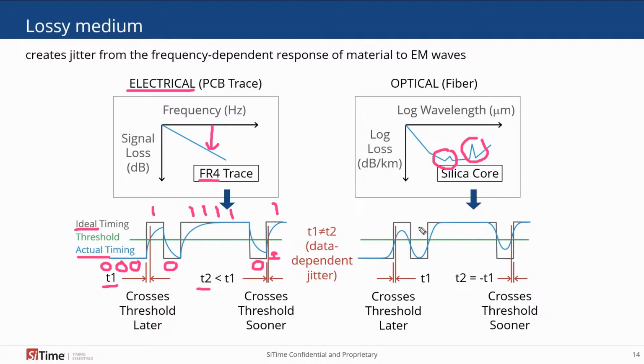And each wavelength propagates through the optical fiber at a different velocity. So some of those wavelengths get out sooner than others, and that creates this chromatic dispersion effect that you see. This pulse looks like it's actually arriving a little bit sooner than the electrical equivalent side due to chromatic dispersion.